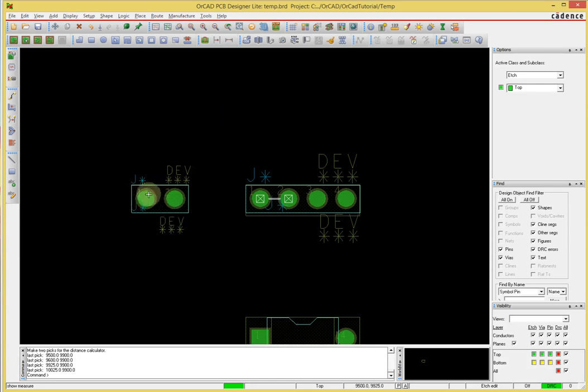I could use a header, a 2-pin male header. I can use the same footprint to hook up a 2-pin female header. I can use the same footprint to hook up a shrouded header. I could maybe even use the same footprint to connect a capacitor, if you bend the pins a little bit and stick them through there. So there's really nothing special about the footprint name, other than you need to make sure that mechanically the footprint can meet the requirements of the parts that you're using from a physical dimension standpoint.